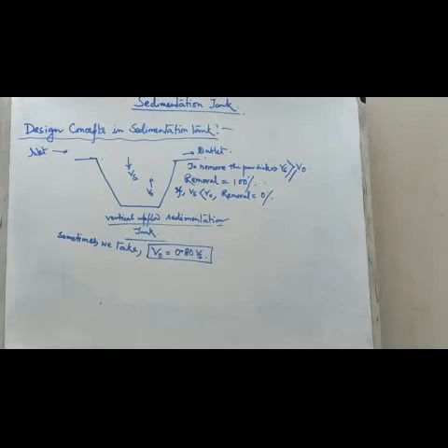Now this liquid rise velocity is the overflow rate, because the water is flowing over the top of the tank into the weir system, and this term is known as the surface loading rate. So what is actually the overflow velocity or overflow rate?